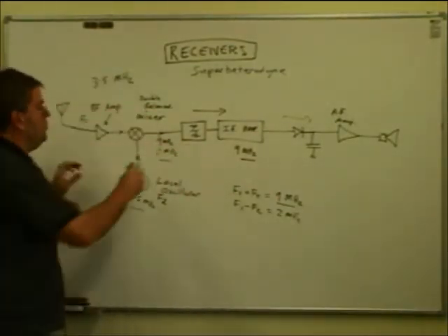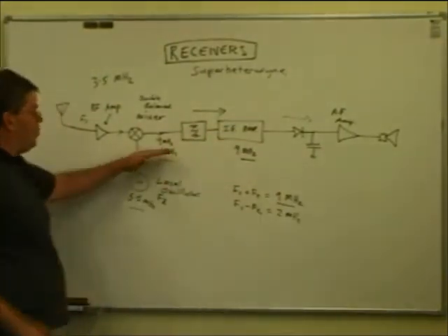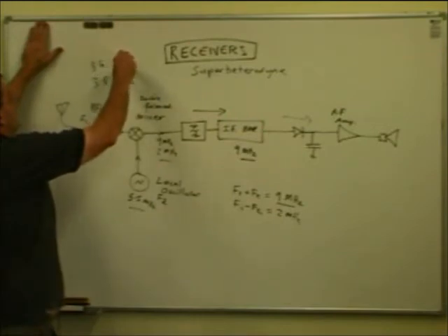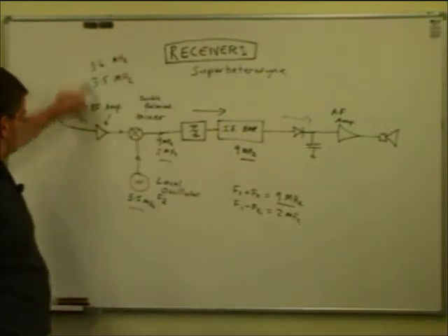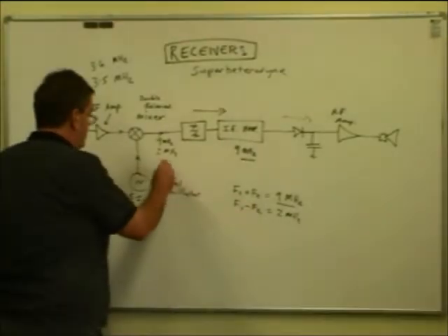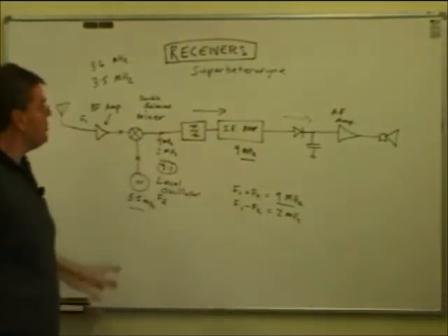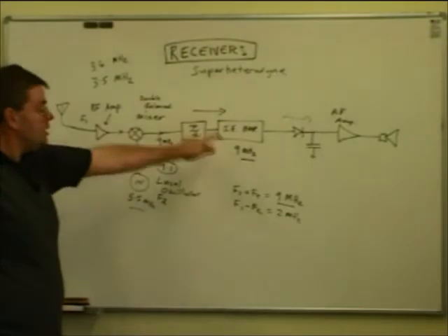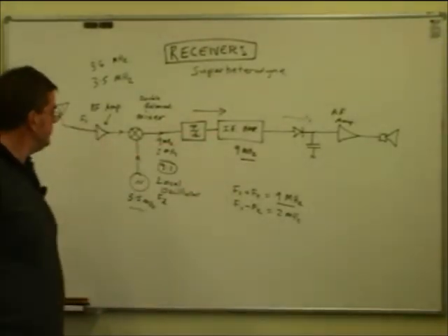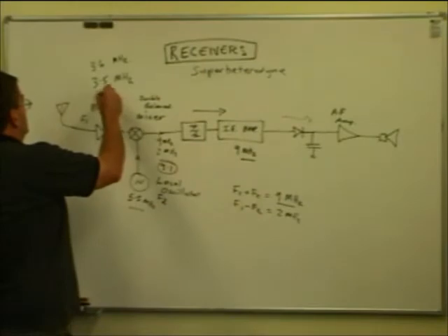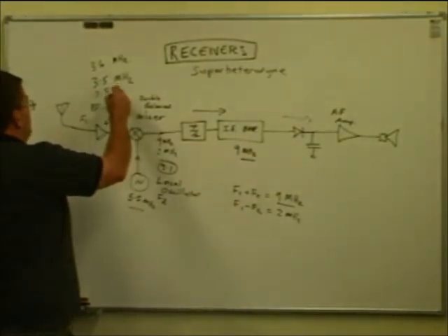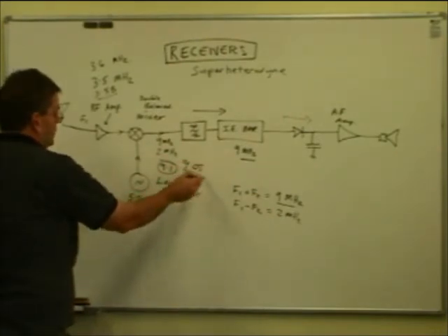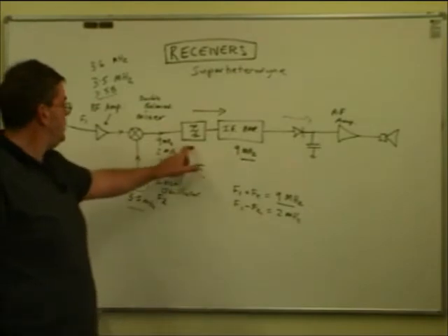And the filter in front of it, the combination of these two, will only allow what we want to pass through. So if there's a signal at 3.6 megahertz, which there often is on the amateur band, 3.6 plus 5.5 is 9.1. We don't want to receive that 3.6 megahertz signal. You can see when it's shifted up using this process, 9.1 won't pass through the filter because it's only very narrow. Okay, 3.55, 50 kilohertz up, that comes through here at 9.05. Still way outside the pass band of the crystal filter.